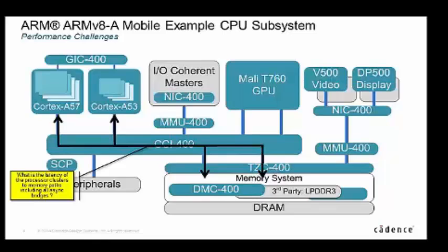The first thing that we suggest you do is to characterize the performance. And this is very simple. Take it path by path, so only one path active to memory at any one time, and actually analyze the bandwidth, latency, maybe sweep outstanding transactions.